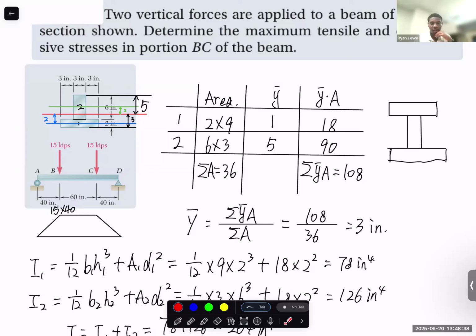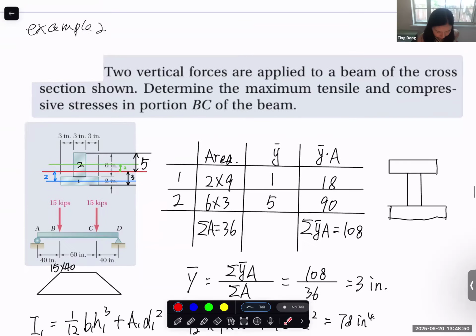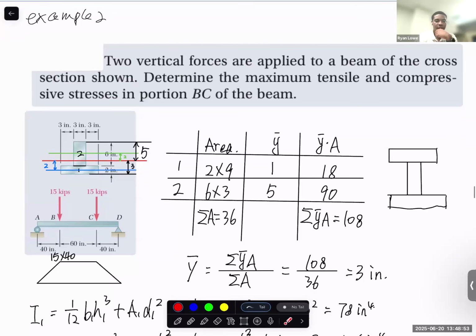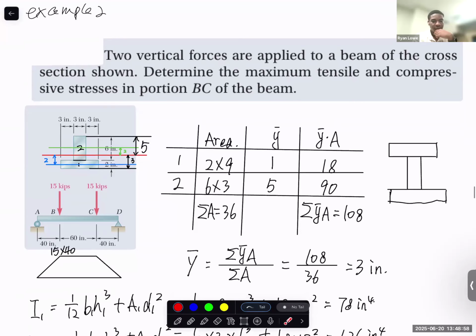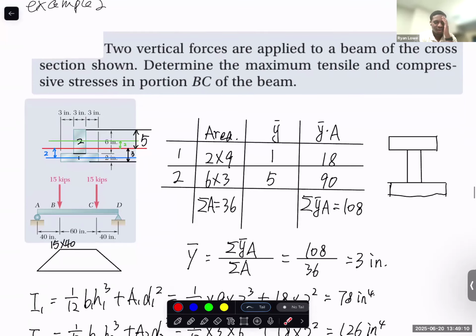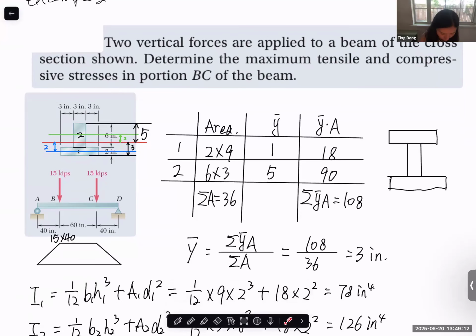All right, I had more of a question about the maximum moments diagram. I'm sorry, I was still confused about that part. I understand that at B it is 15 times 40 because of the moment arm. But if both of them are pointing in the same direction, so like at C, 15 kips are also going down, how does that moment not increase? Is that because the reaction at D... You are talking about why this section is constant, right? Yeah, why is that constant?